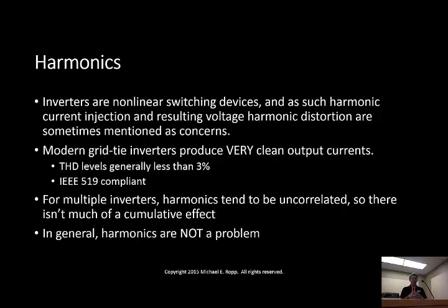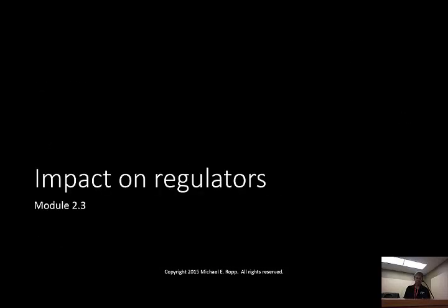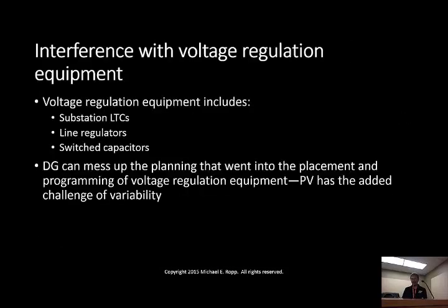Voltage regulation equipment. What we're talking about here primarily is substation LTCs, OLTCs, and line regulators, most of which, as we mentioned before, are automatically tap changing autotransformers, and then voltage scheduled switched capacitors. Those are the main ones.